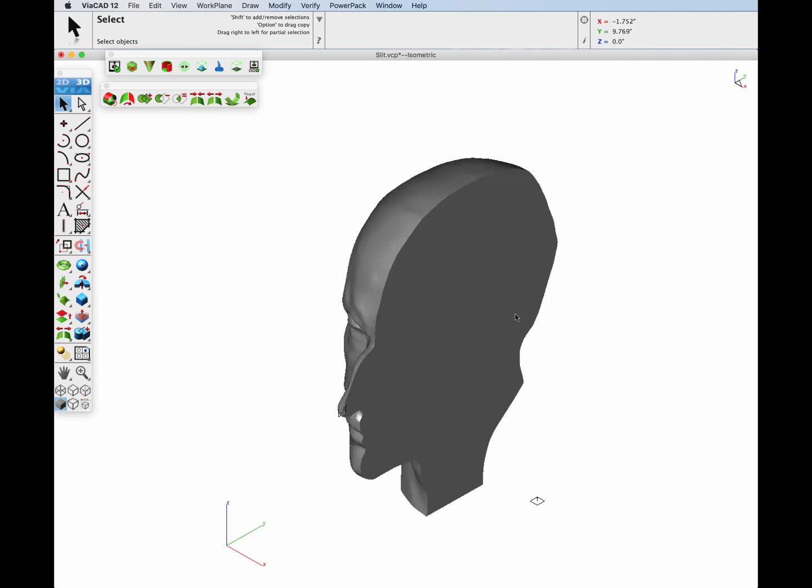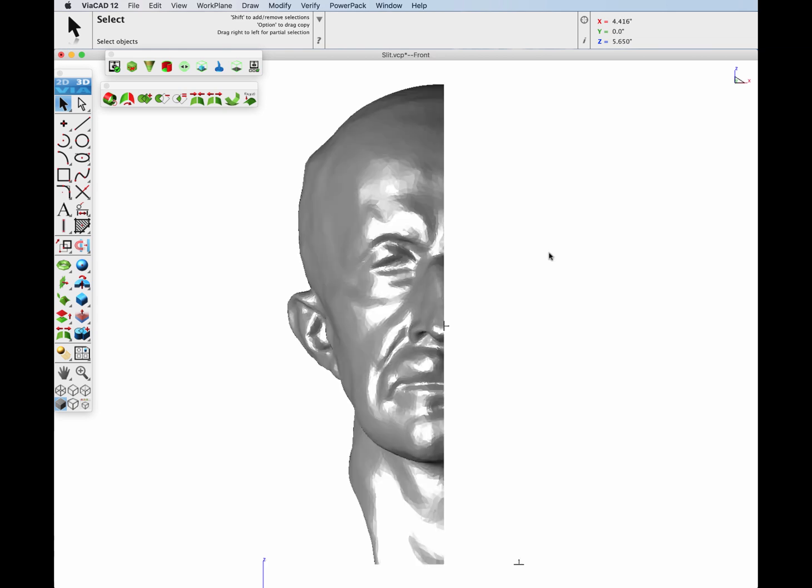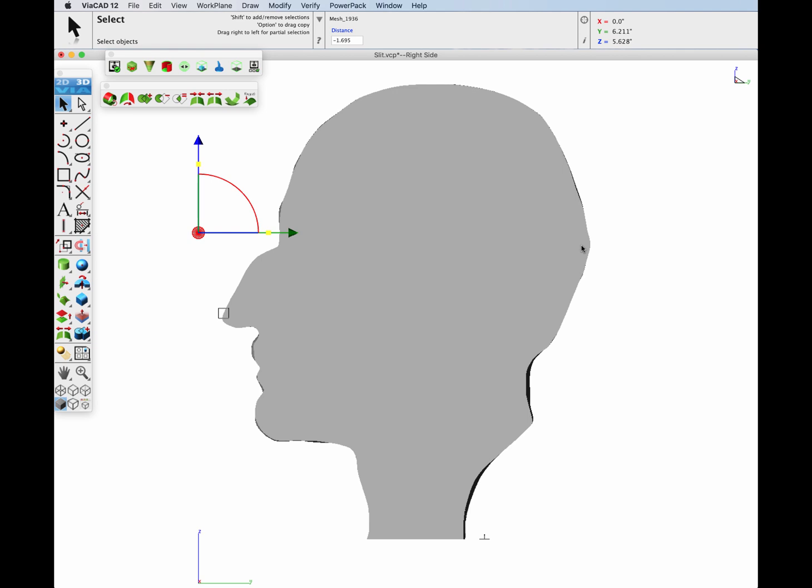and now let's go ahead and add a couple alignment holes using some mesh Booleans such that we can reassemble it when we're done printing. And I will go to the cylinder tool, cylinder mesh, and we'll make this 0.01 inch radius, and let's place it relative to our part, and we'll create 3 alignment pegs.